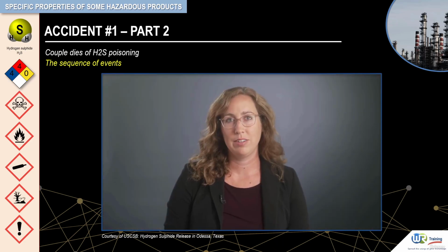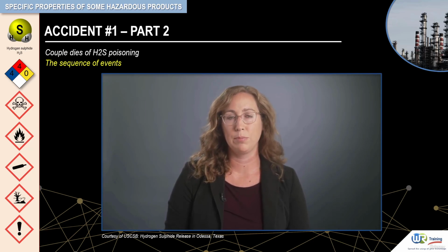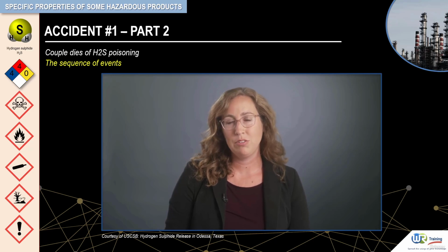Companies must have written lockout-tagout policies and procedures that instruct to isolate all possible sources of energy before employees perform work on equipment. Companies also need to routinely train employees on the lockout-tagout procedures.